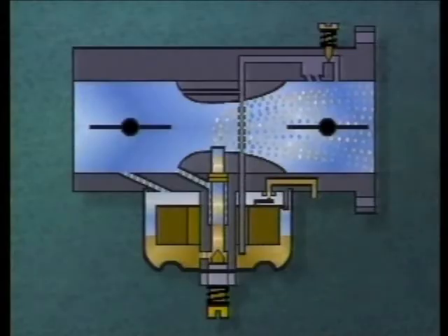In the carburetor we just finished building, you saw two areas where the air-fuel mixture could be adjusted: at the idle circuit and the high-speed circuit. Many technicians thought these adjustments were replaced by fixed jet systems to prevent tampering by consumers or technicians. That is just not the case. One important reason fixed jet systems were developed was to address a common problem: vapor lock.